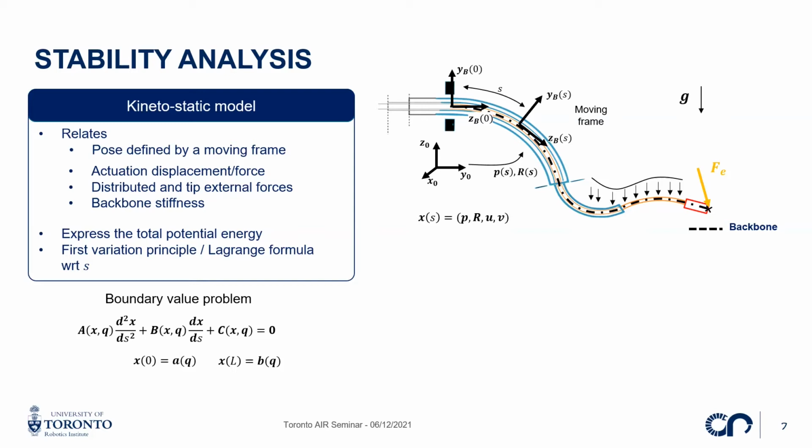This is a good question. So this is about shape control of continuum robots, which is not what people usually work on; they usually just focus on the end effector position and orientation. But basically what people try to do is to approximate the shape by either segments with constant curvature, and then for each of these bending segments you have one value of curvature that you try to control. Or some people try to approximate the whole shape by polynomials, for example, and then you do the control in the parameter space of the polynomial, basically.